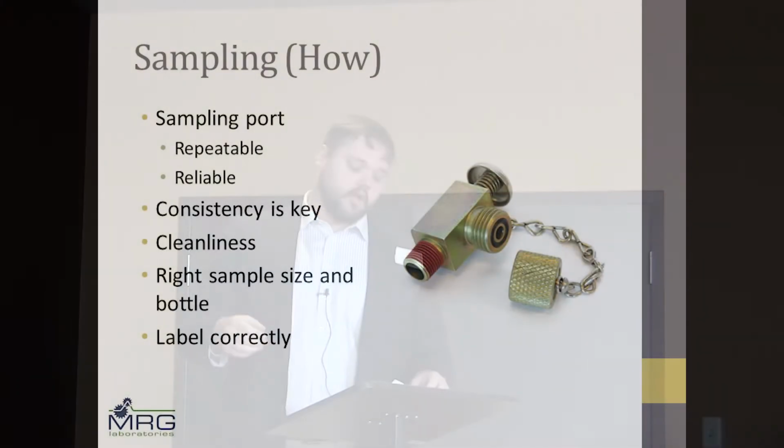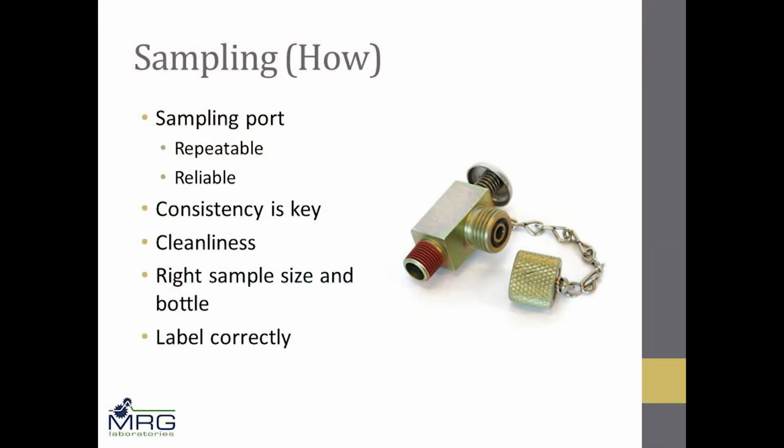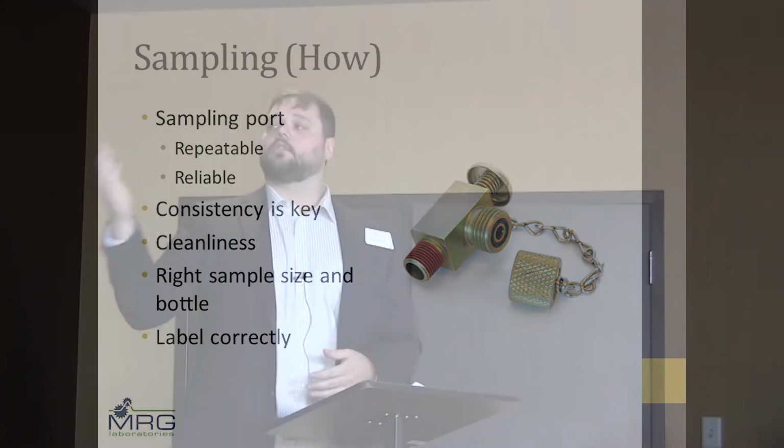When you take a sample, like I said, you want the sampling port because it allows repeatability and reliability in your sample. Doesn't matter if you send out anybody on your maintenance crew to take the sample, they're all just hooking up to the sampling port. So it doesn't matter if Steve, Jim, or Bob goes out, they're all going to get the exact same sample because they're going to the sample port, and it's not having to say, well, Steve has this technique where he fishes the line down in with this. You don't have to worry about anybody doing anything special.